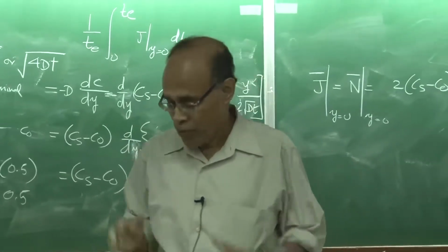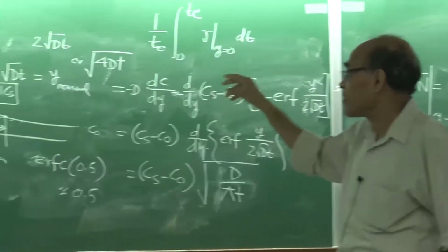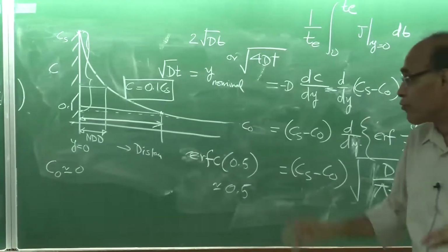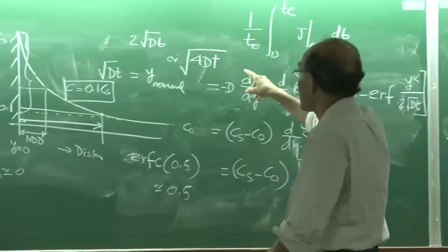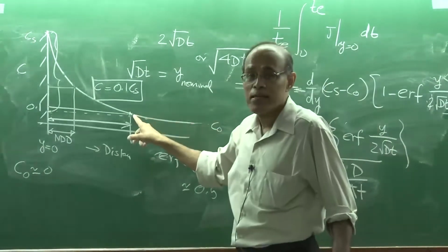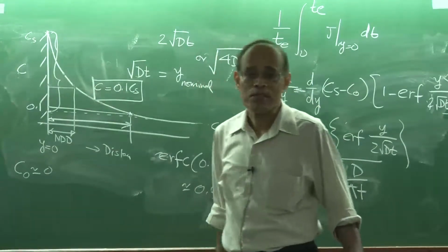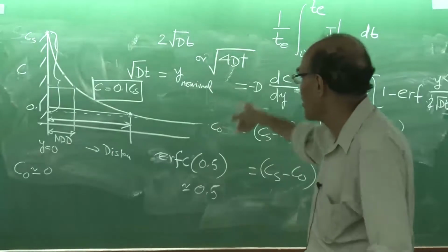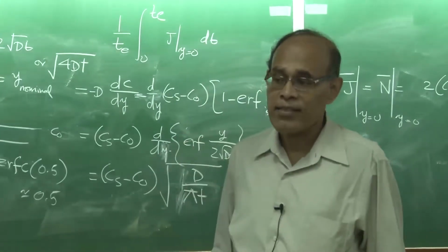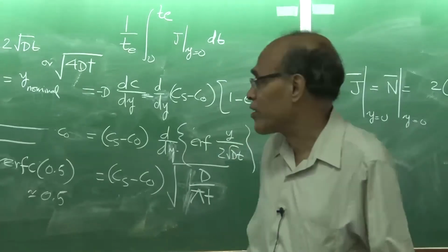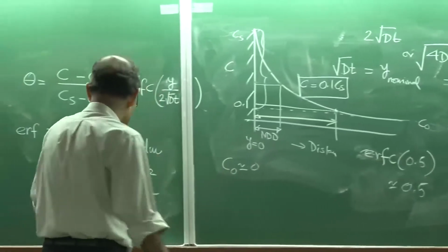and it is the nominal diffusion distance, we say, when the point at which the concentration becomes equal to 50% of the initial surface concentration, and the penetration distance is square root of 4Dt, the location at which the concentration becomes only 10% of the surface concentration. So, we finished our discussion on diffusion, and in the next lecture we will discuss convective mass transfer, which is going to be our last theoretical topic of this particular course.